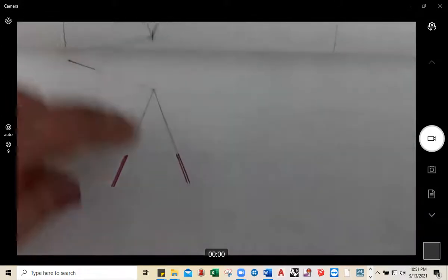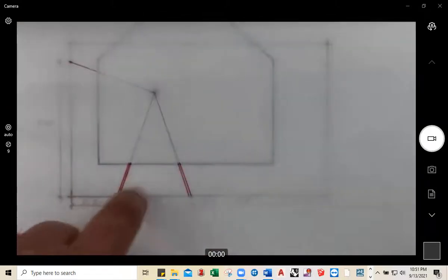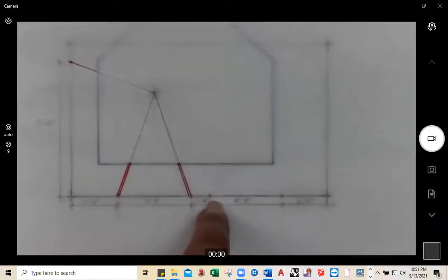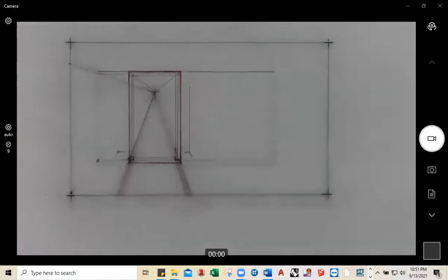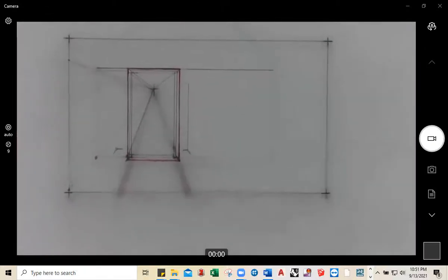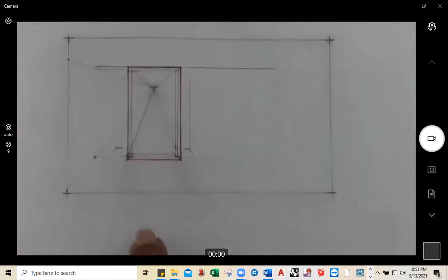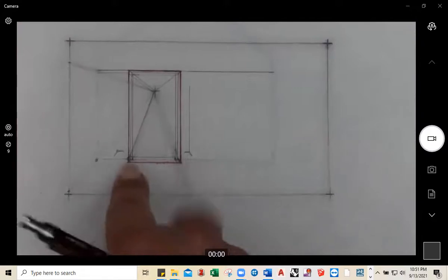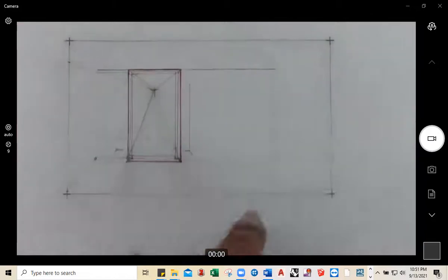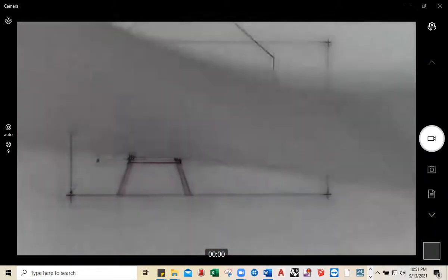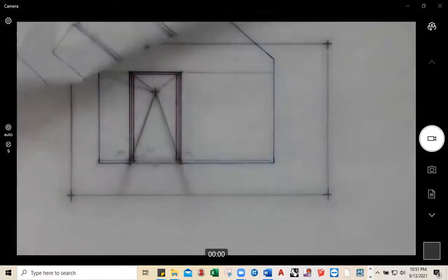So we see some lines starting to be drafted from the picture plane to the center of vision. We did something a little different here. You see 2 lines, but you all are working just 1 line at each of these intersections. And we can start to see where those lines intersect the back wall, you're going to go up vertically. Where the 7-foot line hits the back wall, you're going to go across horizontally to start to create your openings. So let me go to yours specifically here.